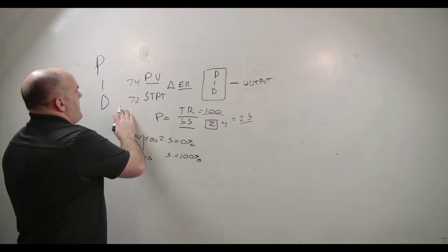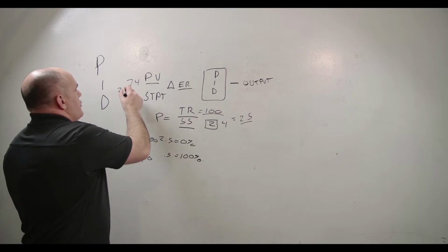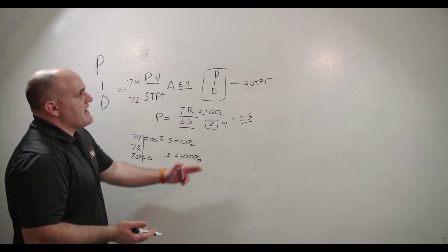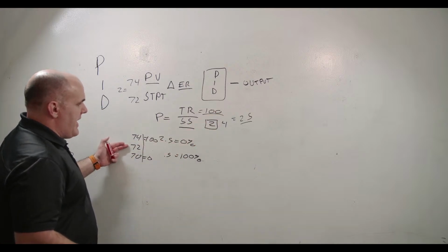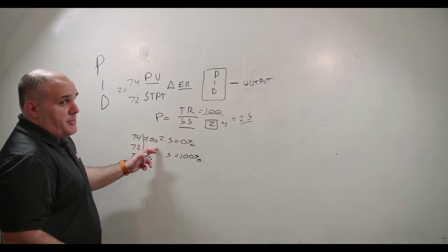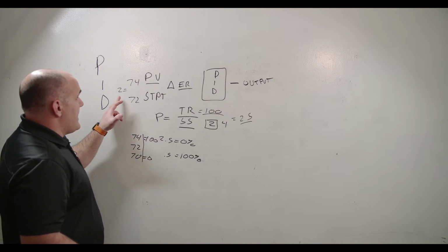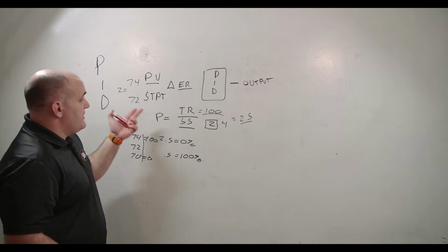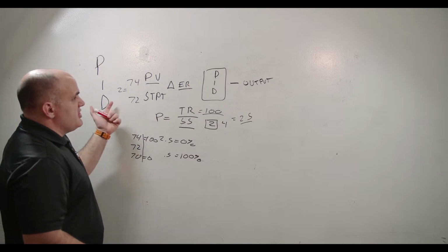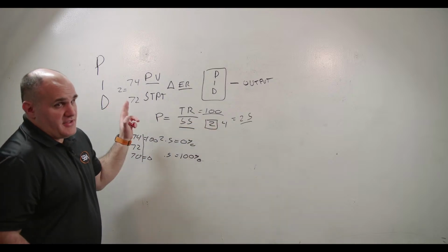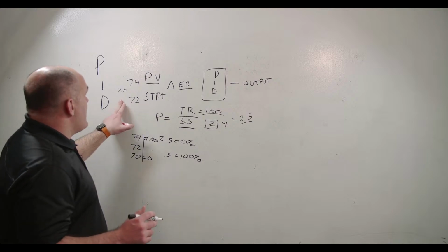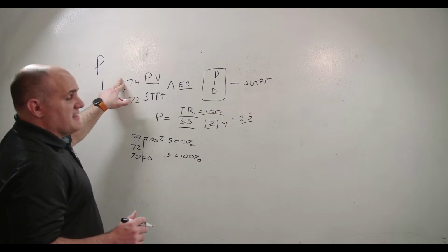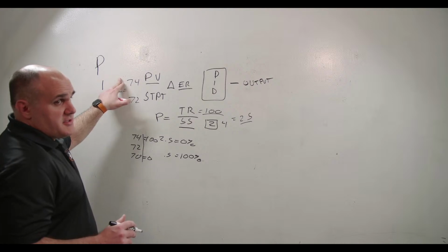But what would happen is that would be a 2-degree error, right? So we would get 50% output. In this equation where I had a 50% bias and I'm preloading the output with 50%, I would already have a preloaded 50, so 50 plus 50 would be 100. You just got to trust me that that's how this works. The important point is that I am fully loaded when I hit the top end of my controllable sensor span.